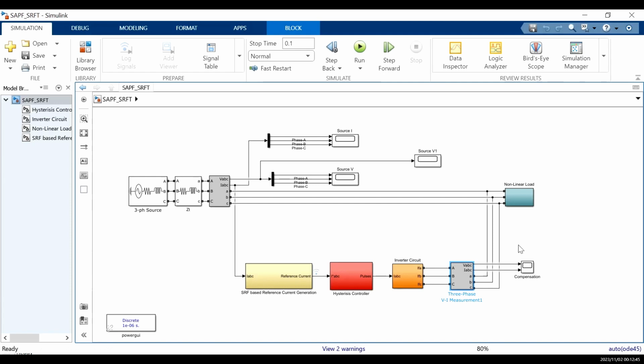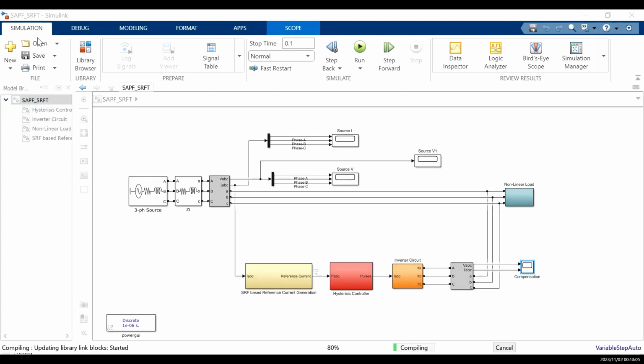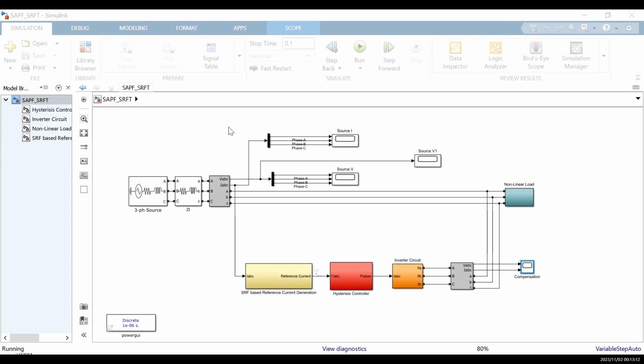4. Renewable energy. Three-phase VSIs are utilized in renewable energy systems such as wind and solar power inverters to convert the DC power generated by photovoltaic panels or wind turbines into grid-compatible AC power. 5. Uninterruptible power supplies, UPS. Three-phase VSIs are integral components in UPS systems, ensuring a smooth transition from grid power to battery power during power outages and fluctuations, maintaining continuous power supply to critical loads.